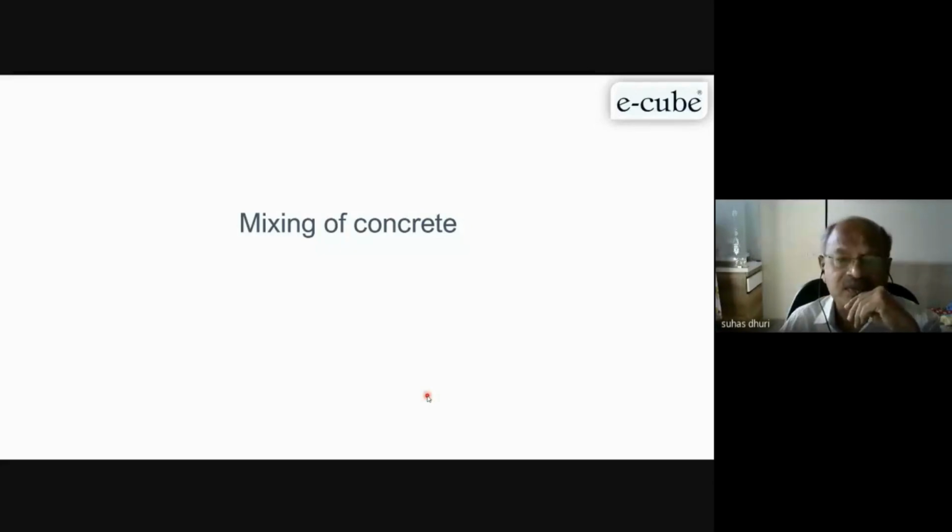You say all ingredients you are planning to use in the concrete are already in the mixer, then mixing time starts. And that may vary from 30 seconds to 90 seconds. Whenever you're using microsilica along with your other material, the microsilica always comes in granular form.